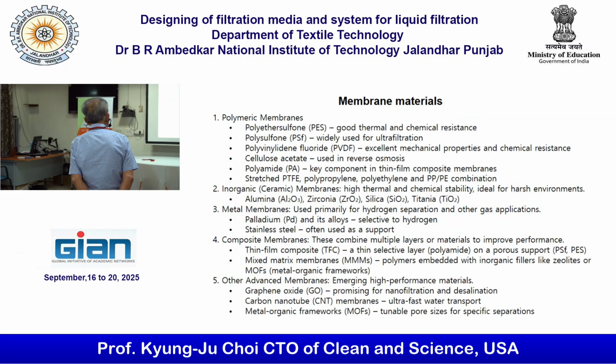Now I'm going into the membrane material itself. Polymeric membrane: polyethersulfone, PES. Good thermal properties, and thermal is important. The last one is PTFE, of course. If thermal is a concern, this is a lot better than any other material. Polysulfone, polyvinylidene fluoride, PVDF. This is quite an important material.